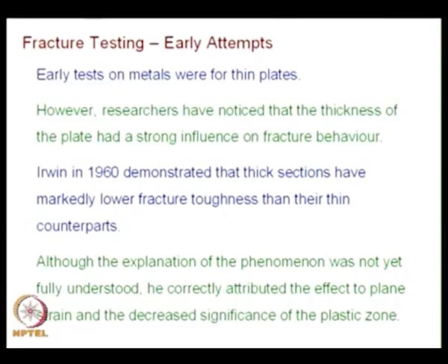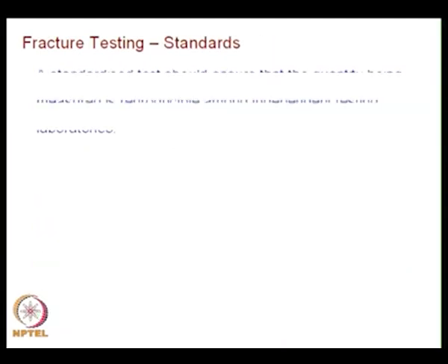See, in the earlier discussion I had mentioned plastic zone is a friend for fracture mechanics, that is what I said. In the case of plane stress, now you know the size of the plastic zone is much larger than in plane strain. So, the experiments reveal the fracture toughness in the case of plane strain is far below what you have in plane stress. An intuitive understanding was provided by Irwin. Later on his result was corroborated by further experiments and discussions.